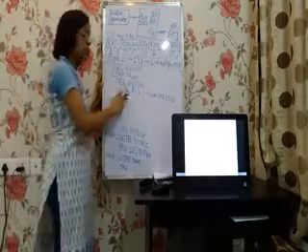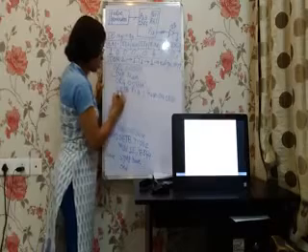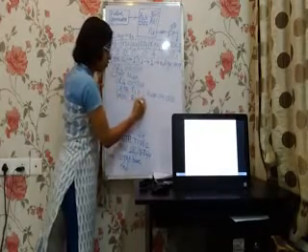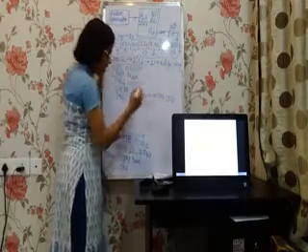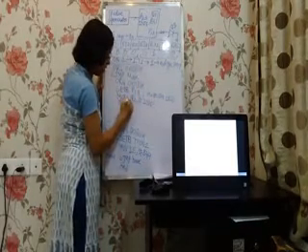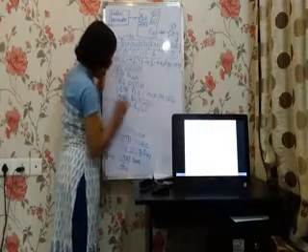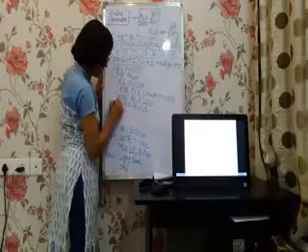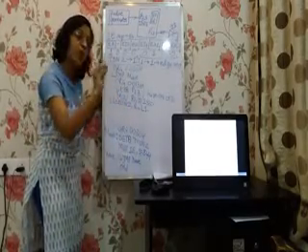Okay, so what will I do? I will wait for some time. For that I use any register. Suppose I use R1. I configure it with some random value, maybe say 255. This is a random value. And I give a DJNZ R1, L1 at the same instruction. This is just to turn the LED on and let it remain on for some amount of time.